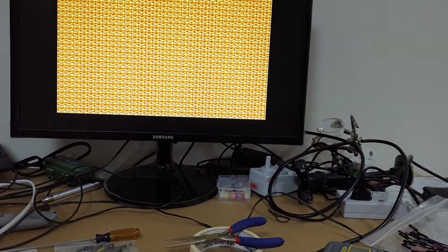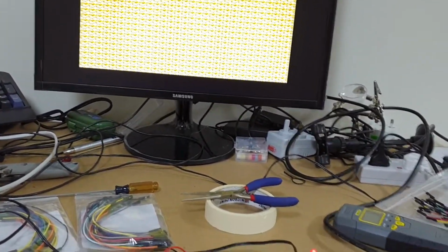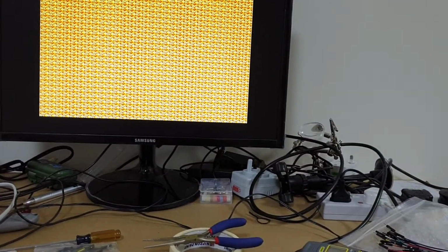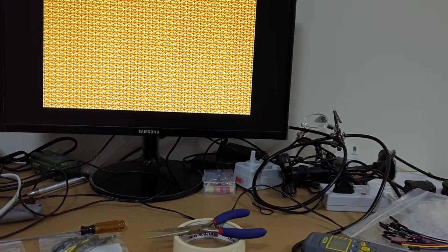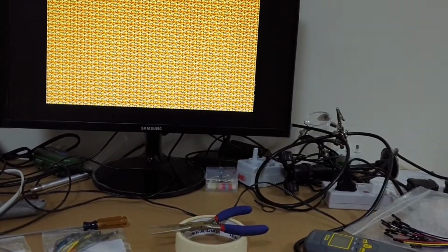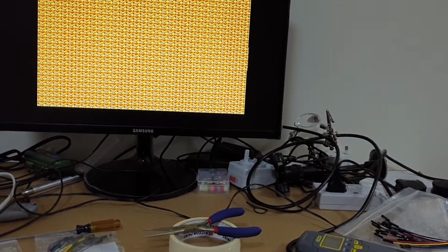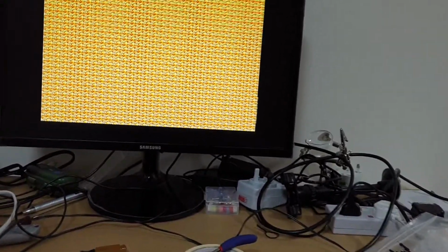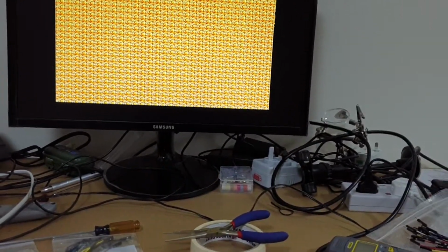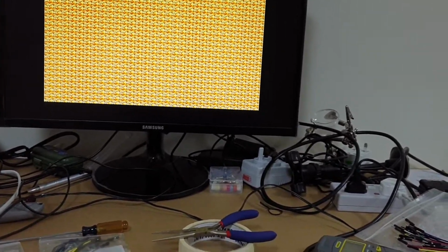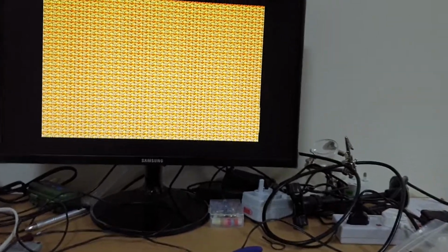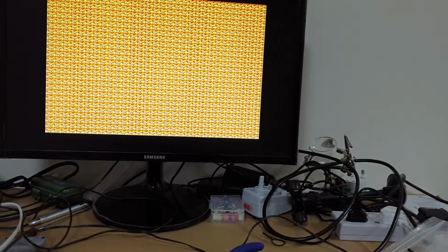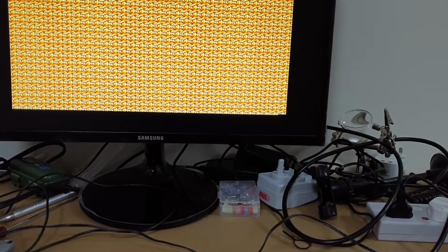All of these edge connector pins are long and hanging deliberately so I can connect stuff to them, but they also potentially cause things like signal reflections, and they would act as little mini antennas as well. So I'm not surprised that I'm seeing this. This is what we get when we're developing through-hole component PCBs. I guess this is why surface mount components were invented, because they're less susceptible to interference. They don't have legs which will act as signal reflectors and all sorts of other weird analog effects. You can expect that, because electrons are rushing around at relatively high frequencies. The clock for this is around 12 megahertz, and internally the board is clocking at 6 megahertz everywhere. So I'm not overly surprised, but I'm really intrigued that this length of wires is generating this. So there we go.